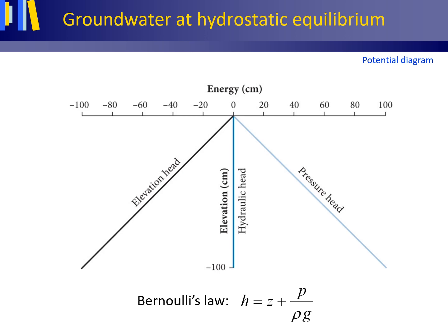When we descend into the groundwater, the elevation head decreases by the same amount in length units in which the elevation decreases. As the water table is taken as reference level, elevation heads below the water table are negative, and the relation between elevation head and elevation can be drawn as a line under an angle of 45 degrees for equally scaled axes as shown.